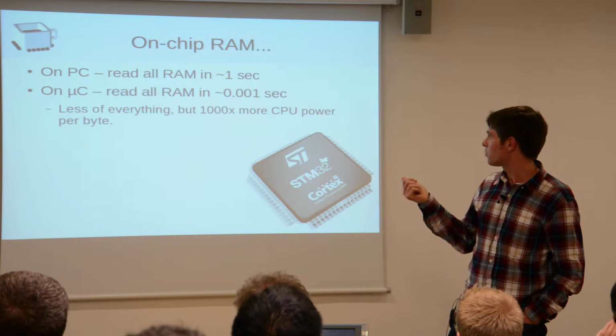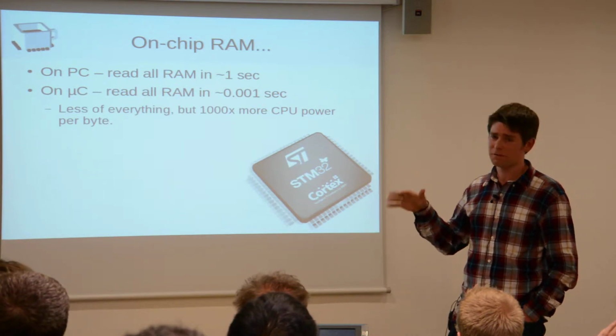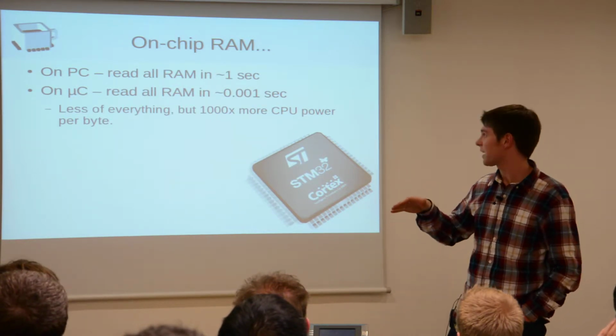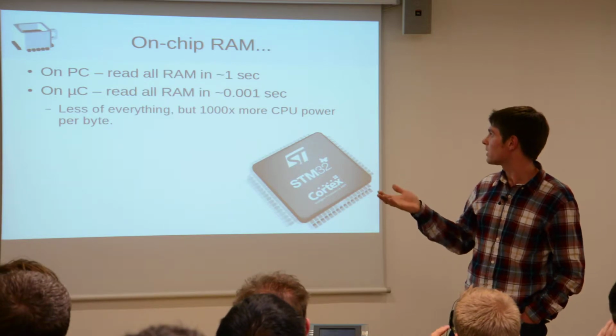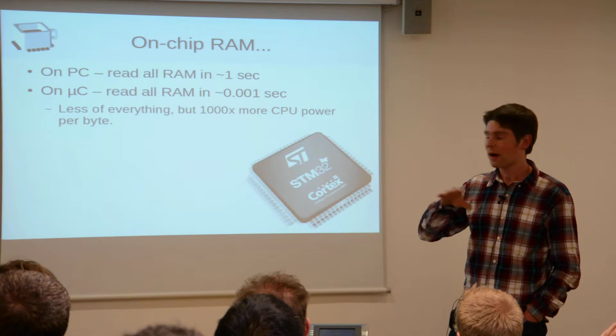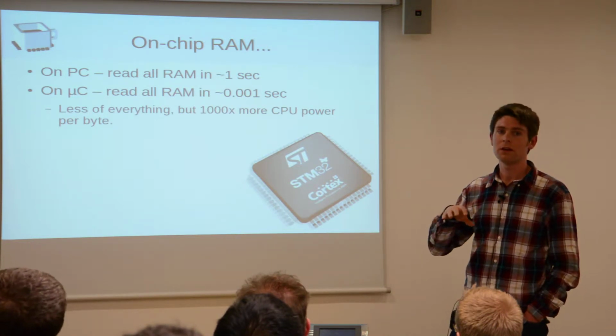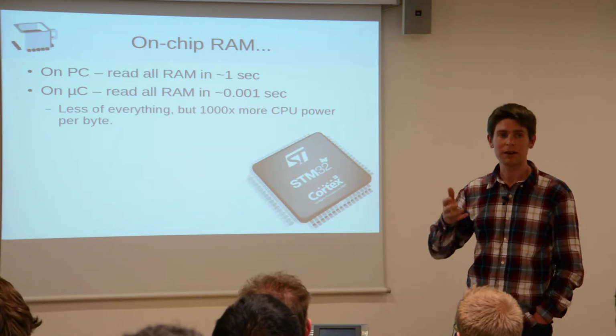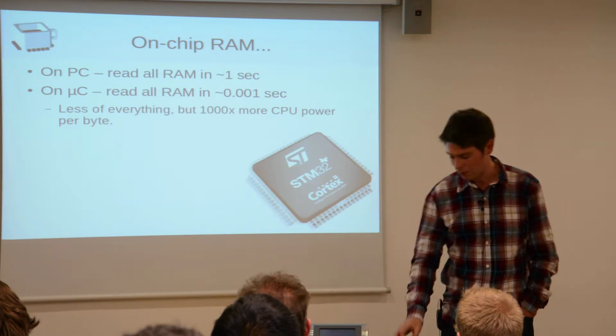So yeah, you've got this weird thing where on the PC, this is very, very rough, you can read all your RAM in about a second, but on a microcontroller, you can read your RAM in a millisecond. So you've got to think differently about how you use the memory and how you use the CPU. Maybe you don't care so much about speed and you care more about making the most of the memory you've got available.